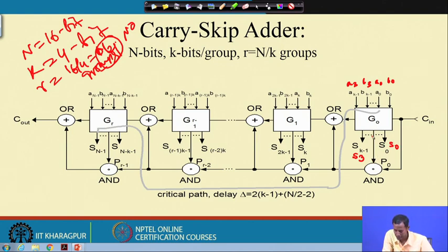Okay. And this line is basically the corresponding P0 value, which I am getting over here, and this is the G0, that means this 4 of this I will get, and this is basically ORed, in each of these the group bit is basically then ORed.